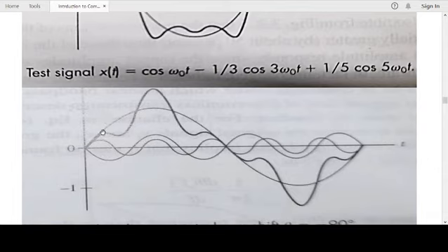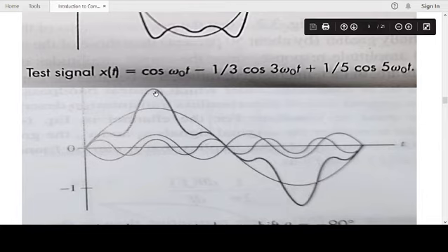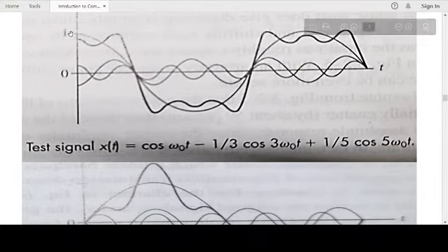You see, the combination of them now gives you this kind of signal. Very weird looking signal. Not a triangular, but kind of a flat plateau, then a triangle kind of sense. And if you keep on increasing the harmonics, it will slowly peak at this point. Note the amplitude here. The amplitude of the square wave was unity, right?